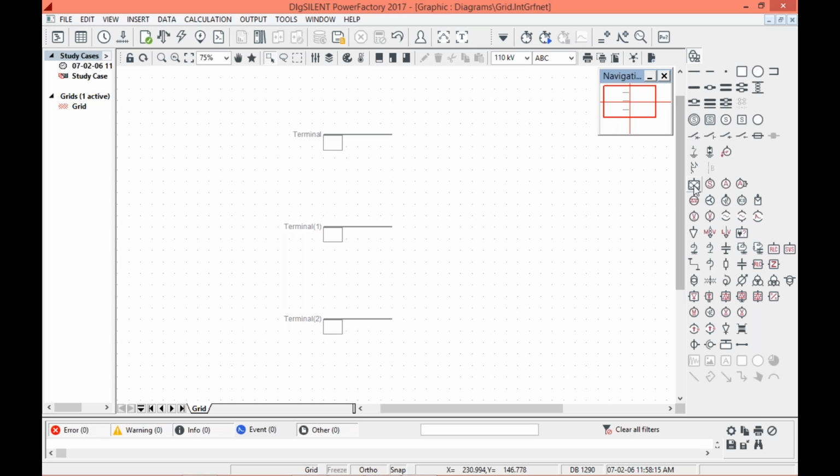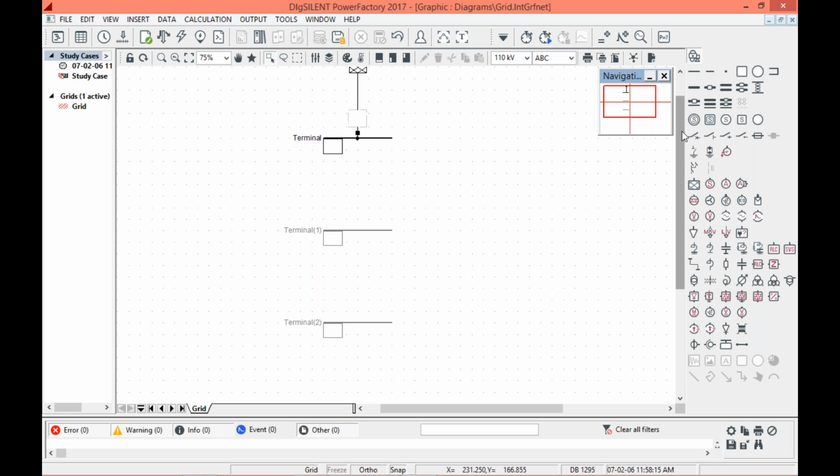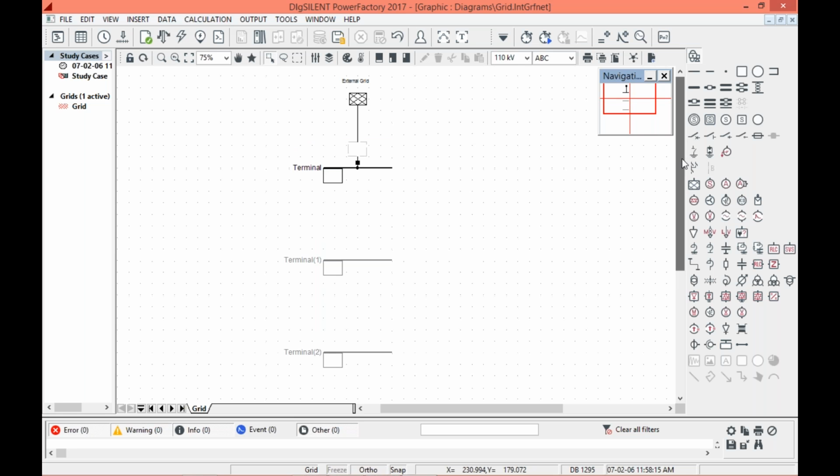After that, let us introduce a grid on terminal. So on introducing grid, see the grid has been attached with the cursor. So just click anywhere. I've clicked once and just drag to this terminal. And for deactivating the grid, just right click of the mouse, and any option that you have chosen will get deactivated.